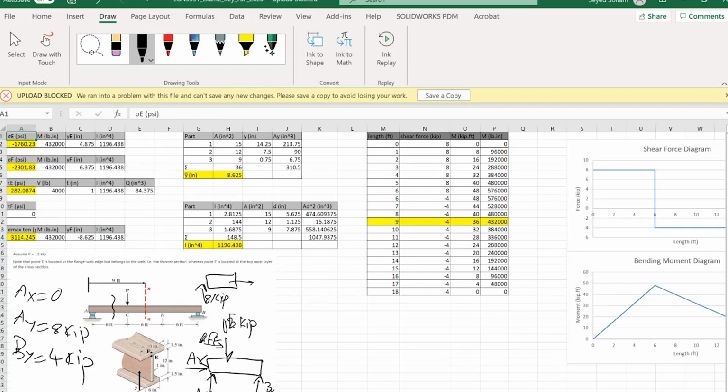And then I have these internal V, N, and M here. What would be the value for the internal shear force? You can establish the balance of forces along the Y direction, and then determine V in this case. So V would be 8. Is it negative or positive? Based on the presumed positive direction for V, this would be a positive V, right?